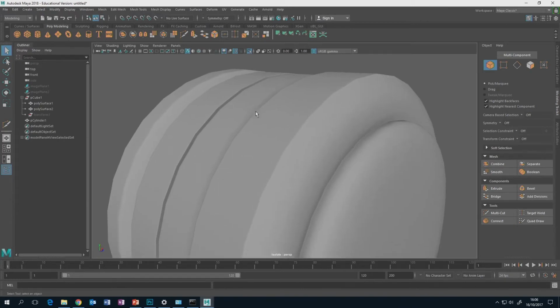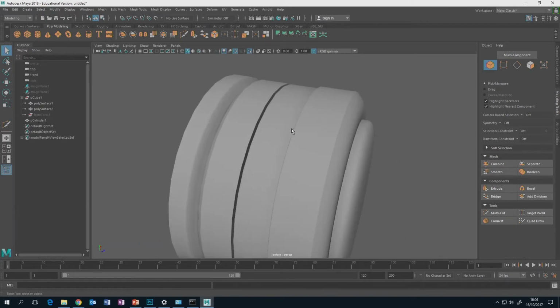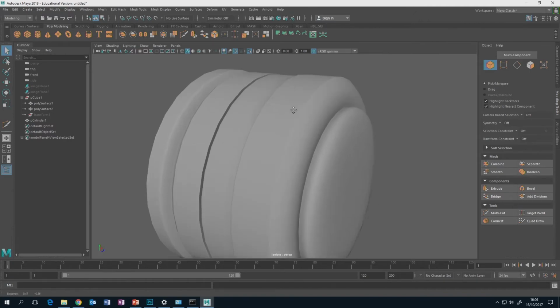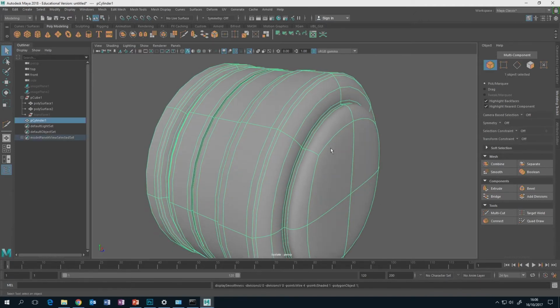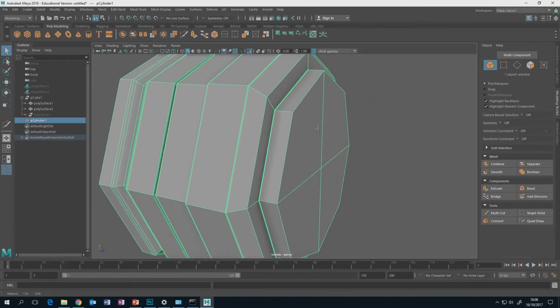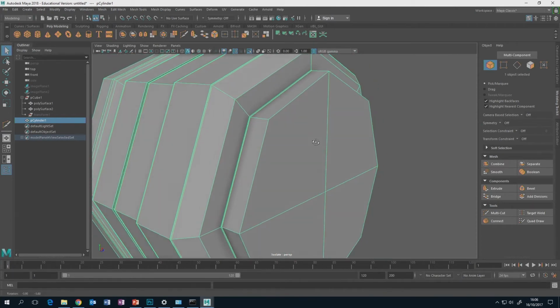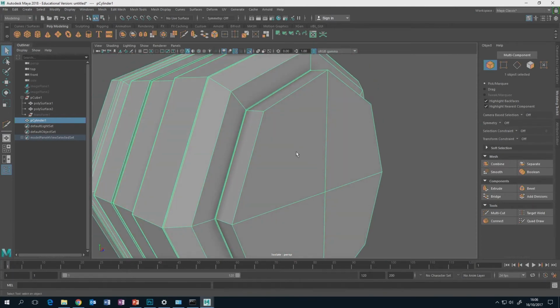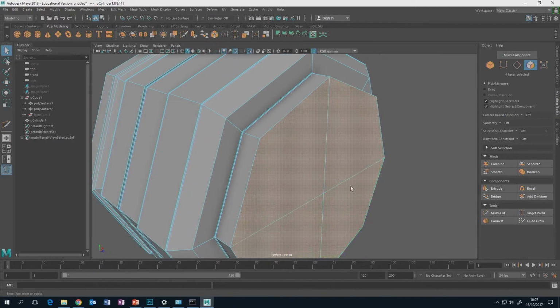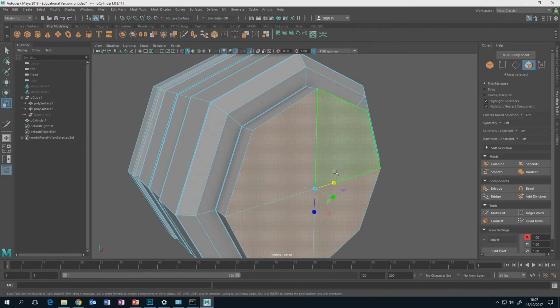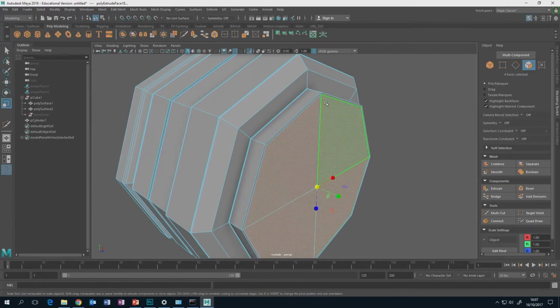Hopefully you can see this is a lot of the same kind of commands being added over and over again. Let's just finish up here with this end part of the lens cap. Again, I'll create an edge loop using that sort of extrusion method this time, where we select the faces here, we go to scale, and again we hold shift, and we just extrude that in a tiny, tiny wee little bit like that, which effectively creates another edge loop.